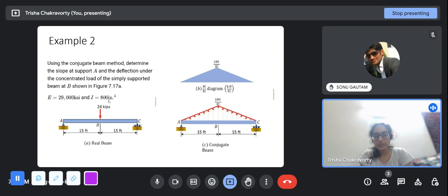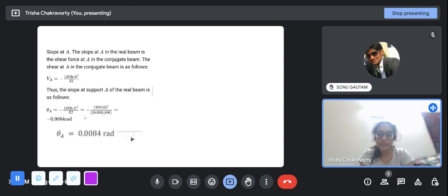In the European units, they usually use inch, pound, feet, but in Indian standards we use kilonewton and meter. I would say just convert everything into newton and meter. You can use kilonewton as well, but stick to the same units. If you use newton and meter everywhere, you will get the deflection in meter, of the order of 10 to the power minus 3 or 4, so you can multiply by 1000 and express the answer in millimeter, which is generally what is expected.